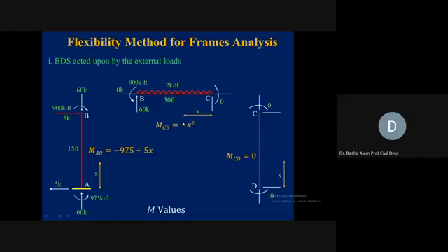Now joint D has to be in equilibrium. So here 0 load is transferred internally, but this 5 kip is externally applied. Why are we not bringing this to the horizontal member? Because if we bring it to this horizontal member, then it has to be supported by C. From C it will come to the vertical member, but then there is nothing at D to support it. So it means that this 5 kip cannot travel towards the right by adopting this BCD path. It has to adopt this BA path.